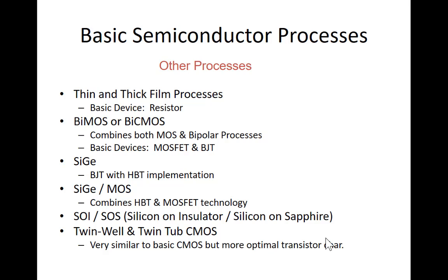Silicon germanium. So instead of using a silicon process, we have silicon germanium bipolar transistors. Silicon germanium bipolar transistors are really fast. So if you need a lot of speed, SiGe might be the route to go, although in many cases, companies will start a design in SiGe because they think they need the speed, and by the time they get nearly done with the design, somebody else has figured out how to do it in CMOS, and the market for SiGe is not there.